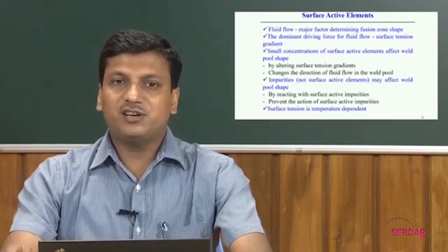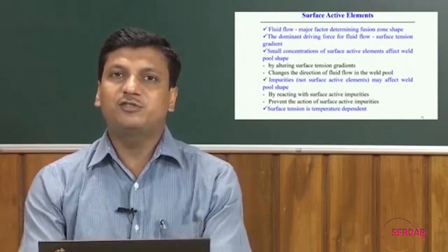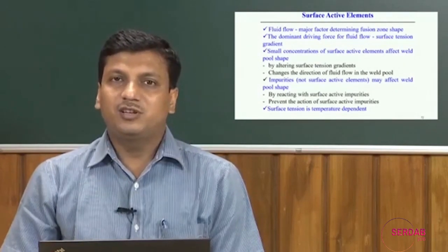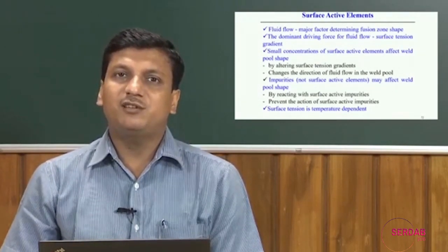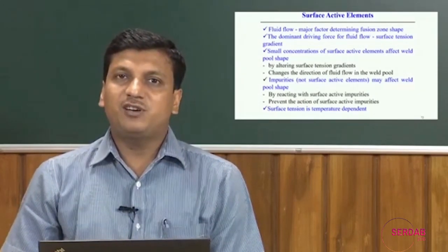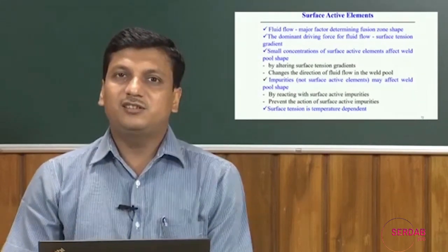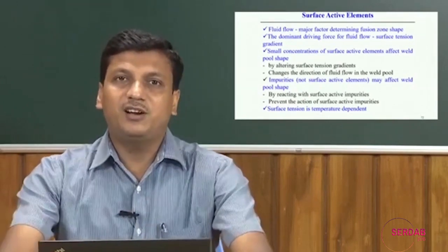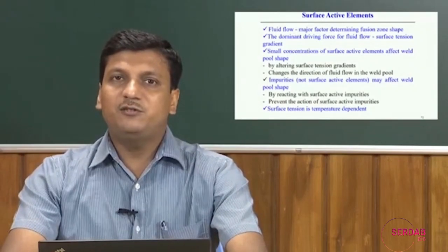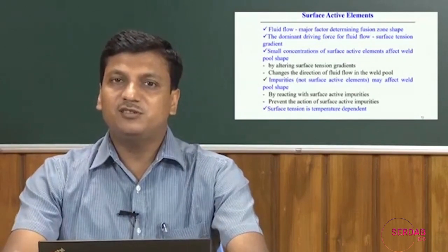Now, sometimes a small concentration of the surface active elements affects the weld pool shape. For example, if we consider pure iron, and if we consider steel as a binary system of iron plus one surface active element, then between pure iron and this binary alloy, the nature of the material flow can differ depending upon the presence of the surface active elements in the second case.